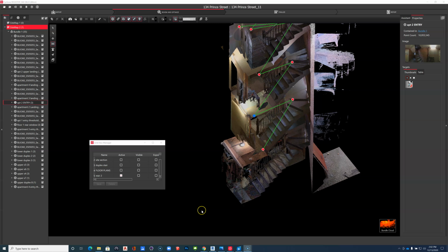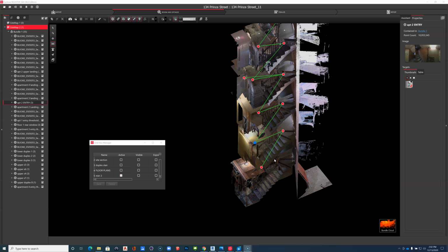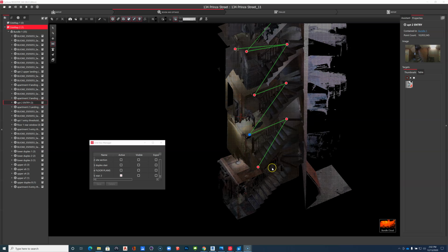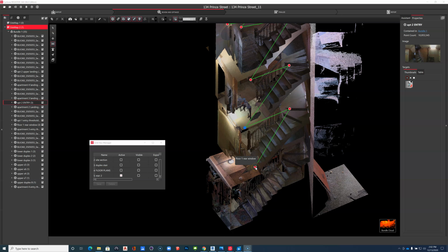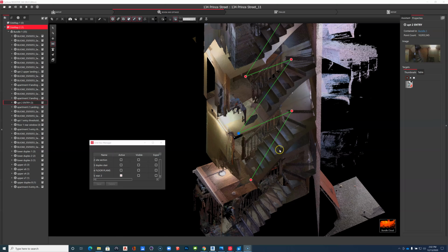Stair by sketch will also be used to model a similar stairwell. The main stairwell of the building has a combination of standard treads and winders and then a landing and that type of thing. So I'm going to take the same floor to floor, which would be level 2 to 3, right, which we just modeled inside the apartment.